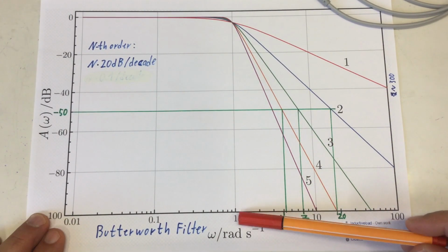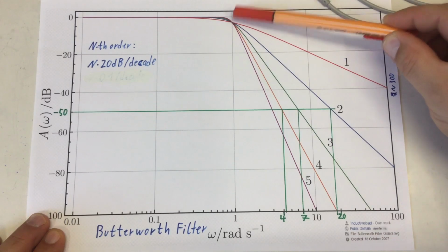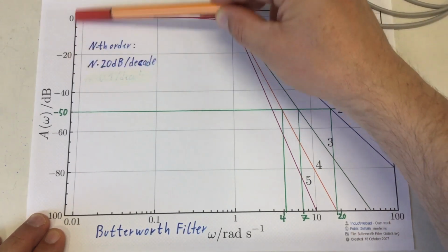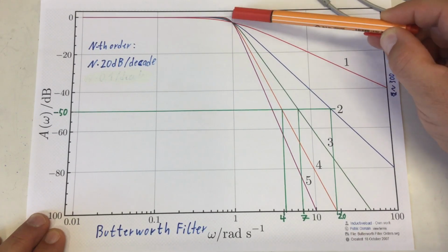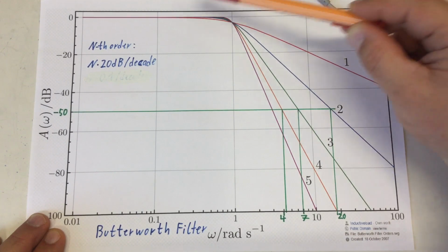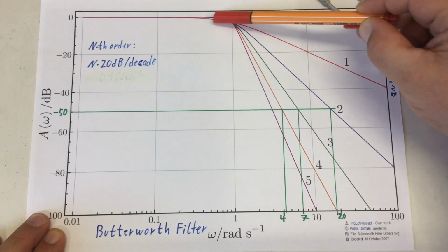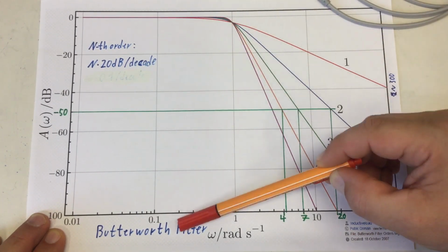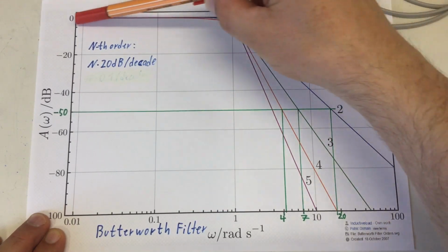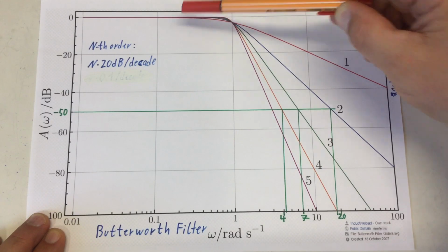I say usually because at the cutoff frequency we are already down minus 3 dBs. Logarithmic scale, that means about 30%. That might not be acceptable, and you might want to design your filter so that your analog signal stays within an area where we are truly at the 0 line.